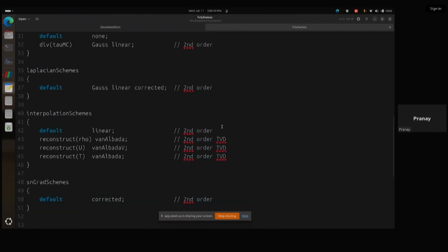And interpolation is, assume you have two cells, and you know the value at one center, and you know the value at the center of the other cell too. But do you know the values in between? It would be wrong to assume, because the cells would not be strictly rectangular in nature. What if it is triangular? What if it is prism, tetrahedral, or altogether a very quadrangular element?